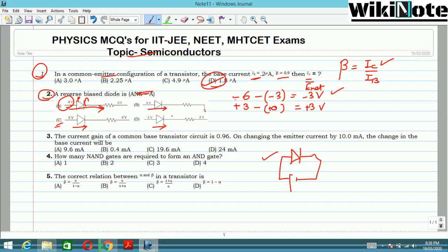So this is 0 volt, so 0 should be positive 0, then -2 volt, so minus in bracket -2 volt, so this is going to be +2 volt. So the third diode is also going to be forward bias, and the second diode is also going to be forward bias because the net voltage is positive. And for the last, this is 2 volt, take down its polarity, positive, then this is +2, so minus in bracket 2 volt, so 2 volt is positive, so 2 minus 2,